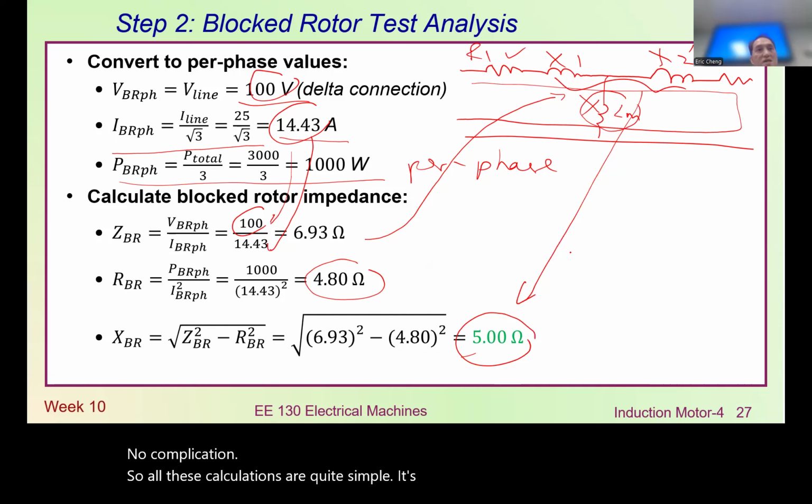Okay. Then for the magnetizing component, now we try to get it. For that low impedance, 84.4. Just now we calculated that impedance, right? That impedance could be due to the combination in here, right? So to get the exact value, this 84, we can subtract this one from here, then we can therefore get the XL. So that's one of the ways we combine the two tests to get the magnetizing inductance.